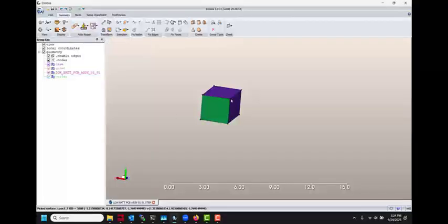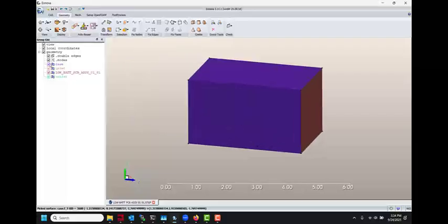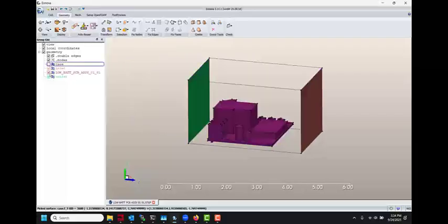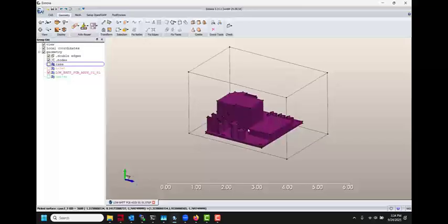There we go. So you can see now what I've got. Zoom in here. I've got my case, I've got my inlet and my outlet. So we're going to have air coming in through here, going over it and exiting. And the task is to use the solver. At this point we're not going to make any decision about what solver we're going to use. We're just going to create a valid mesh to do the conjugate heat transfer of all these components.